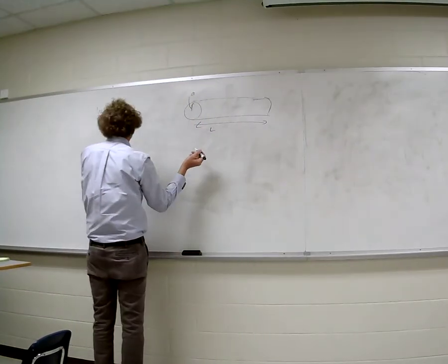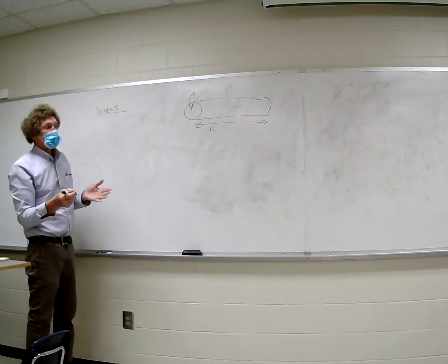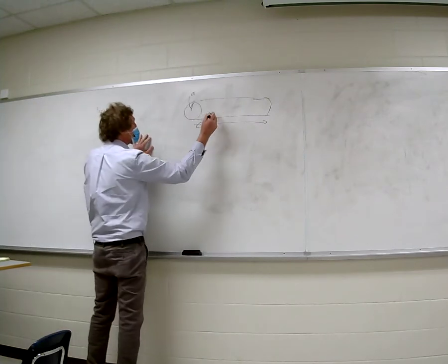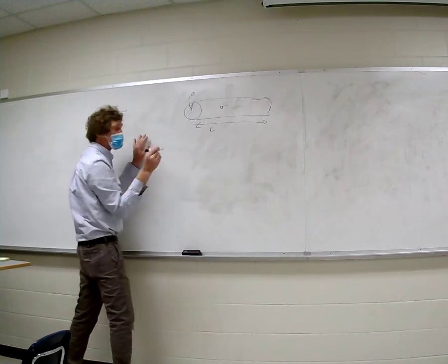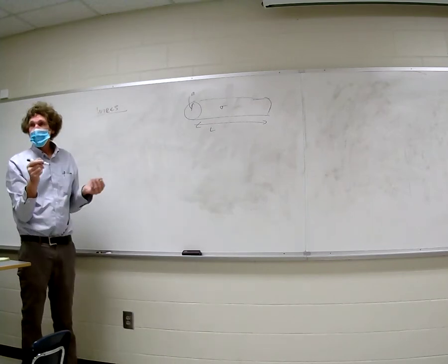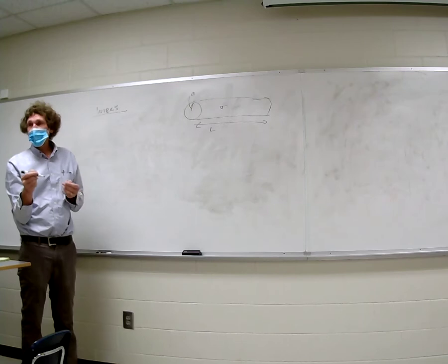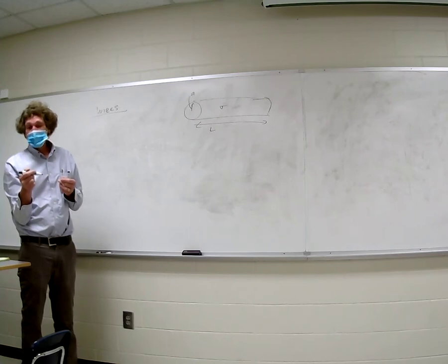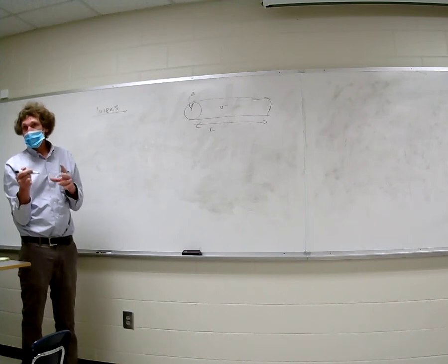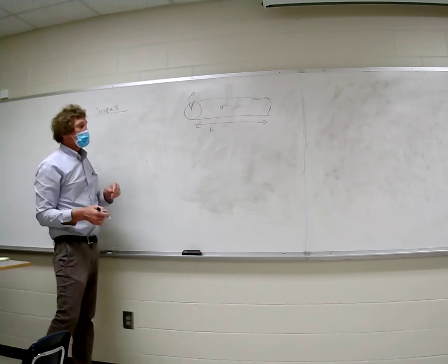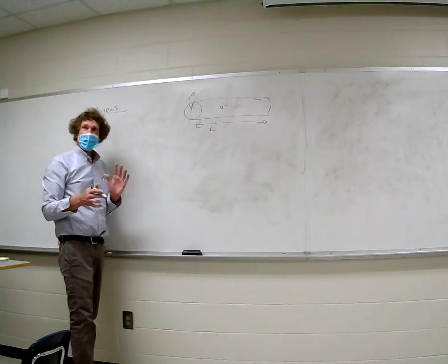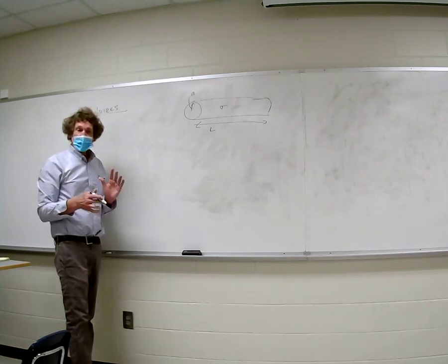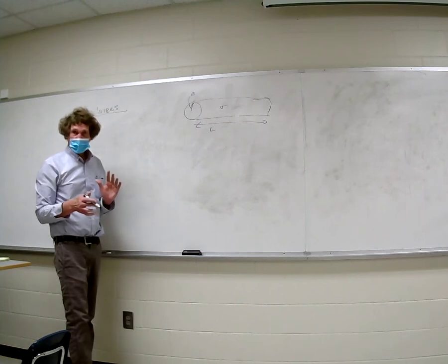And if you take a look at that, we could go through the math on this, but you know that for this type of arrangement, if it's a wire, it has a certain conductivity sigma that's very high. 10 to the 7th is typical, 10 to the 8th. About 5.8 times 10 to the 7th, 1 over ohm meters would be the units, and that would be for copper at room temperature. But there's a variety of things that can be done to change that somewhat. All good conductors are about 10 to the 6 to 10 to the 8, 1 over ohm meters, or Siemens per meter type of conductivity.